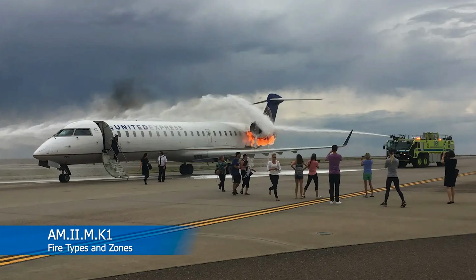All right, the most obvious zone of an aircraft that you're going to see a fire is the engine. Why? Because that's where the fire is at. An engine is nothing more than a controlled explosion happening either over and over again if it's a reciprocating engine, or continuously if it's a turbofan jet engine. Now, if something happens with that engine that gets a little out of order, you could easily have a fire. If you have a compressor stall or an uncontained, what do they call those? The engine comes apart. You're easily going to get a fire.